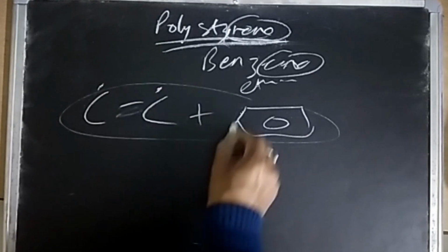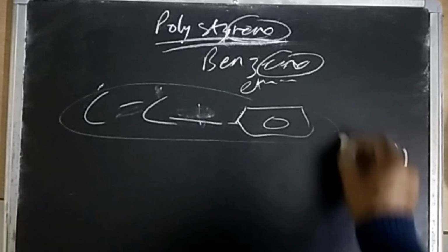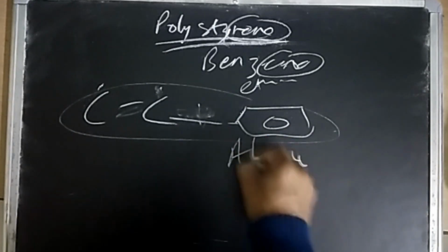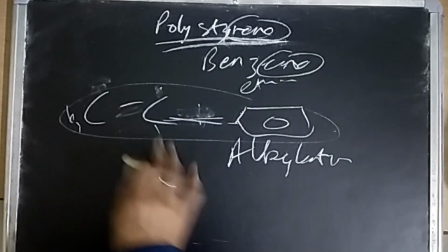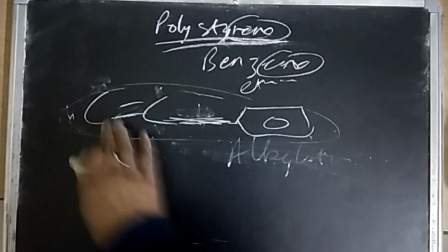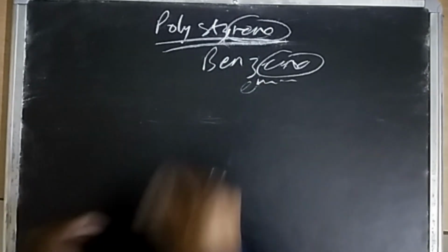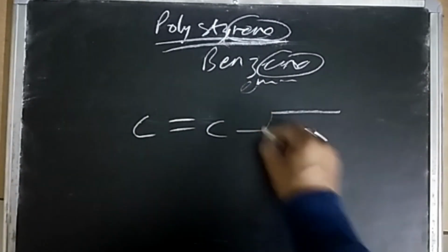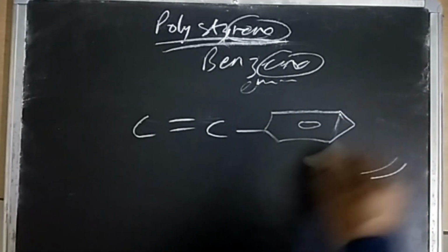This goes over here, this comes here, and the main process that happens is first the alkylation, like this comes here, this becomes CH3, and then we remove hydrogen from here to make it styrene. So finally styrene is formed by first alkylation, adding this, and removing the hydrogen, dehydrogenation. So alkylation and dehydrogenation will finally make the styrene, which is this. Okay, styrene, benzene, ethene, styrene.